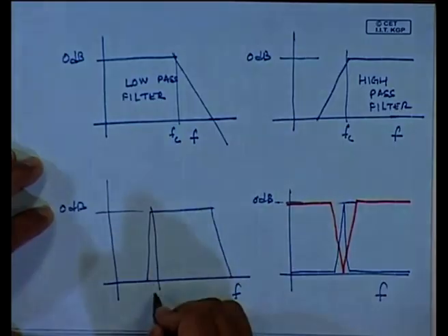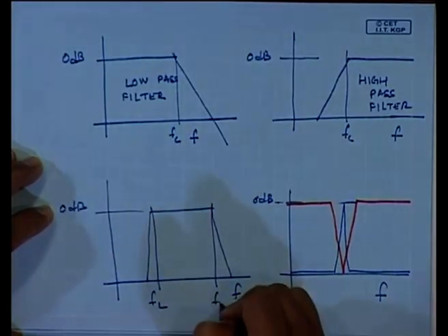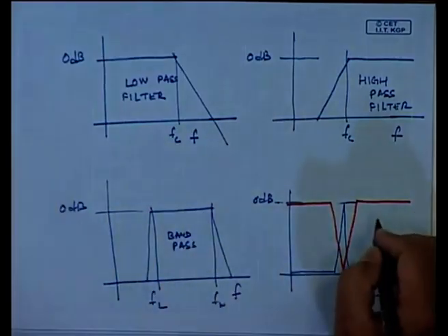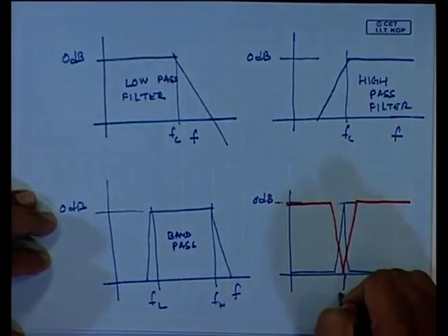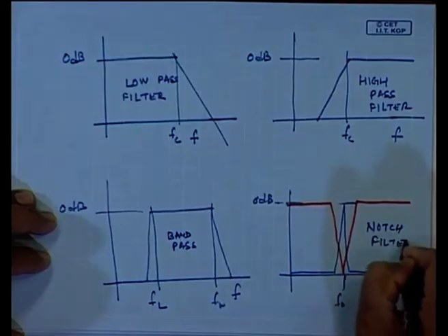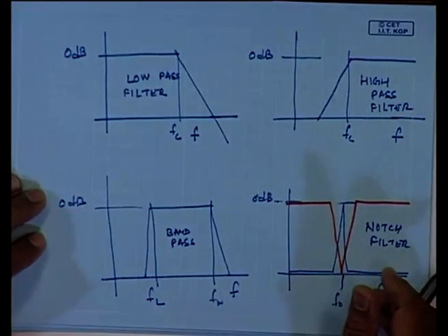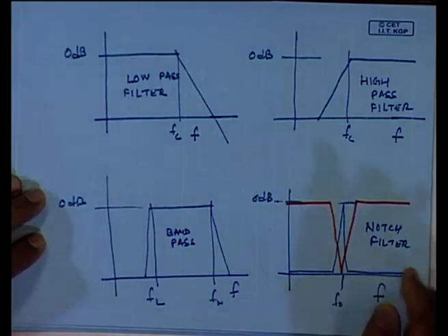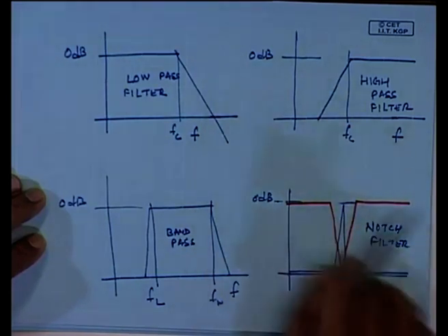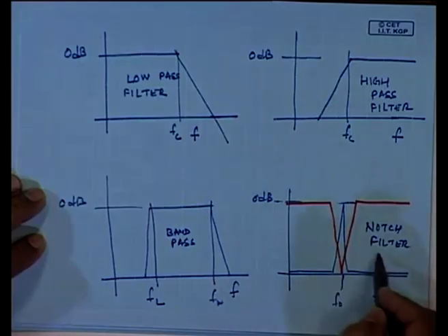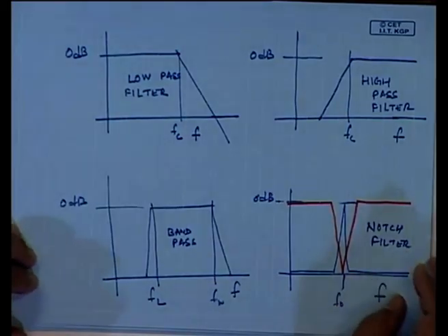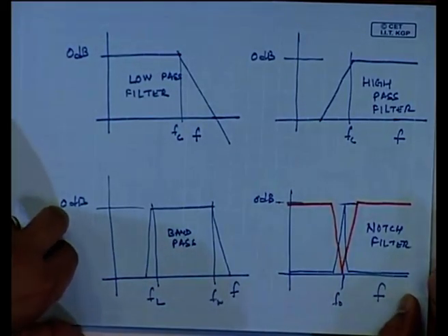and this is, as you know, the band pass. And this one will kill a particular frequency, and this is known as a notch filter. Notch filter, I will just give an example. For example, in many electrical circuits we have a predominant frequency of 50 hertz. So, if I put a notch filter of 50 hertz, it is going to remove that 50 hertz signal from the actual signal. So, this is where a notch filter is used. If I have such filters, I can also have an estimate of the frequency response of the signals.